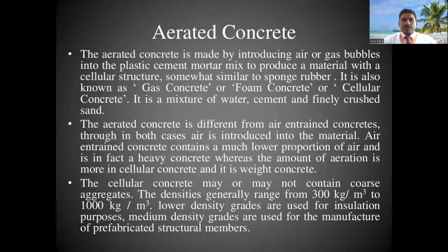So the self weight and dead weight of the concrete will be reduced, the concrete becomes economical, and the cost of construction is also reduced. That is the aerated concrete. We can also call it gas concrete, foam concrete or cellular concrete. This we saw in the last lecture.